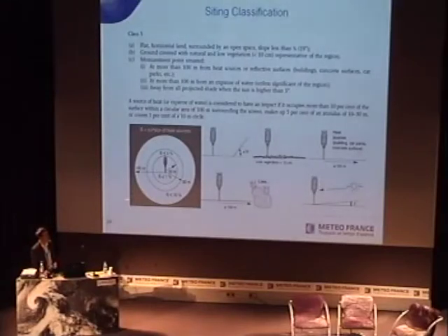You don't want heat sources. You don't want concrete nearby, because it accumulates and radiates a lot of heat, and you don't want a bad measurement due to that.